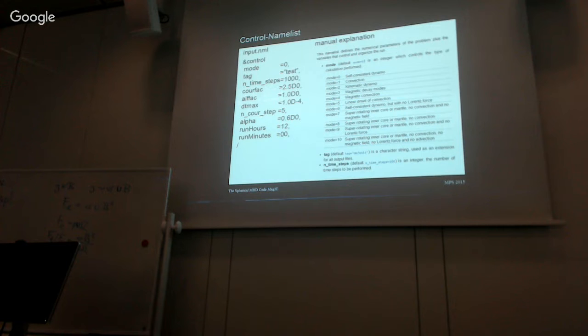So the time step is an adaptive time step, and it's adapted according to the flow velocity and the Alfvén velocity. And then if you make these factors larger, you're more critical. So basically you adapt more frequently, or you make your time step smaller even than you need to resolve an effective flow velocity or an Alfvén velocity.